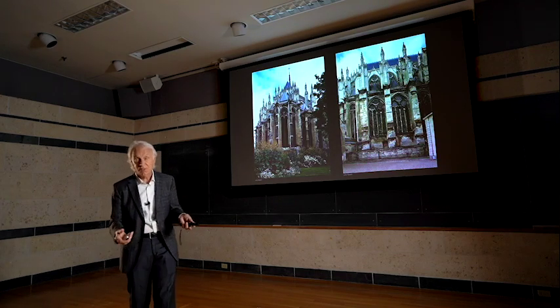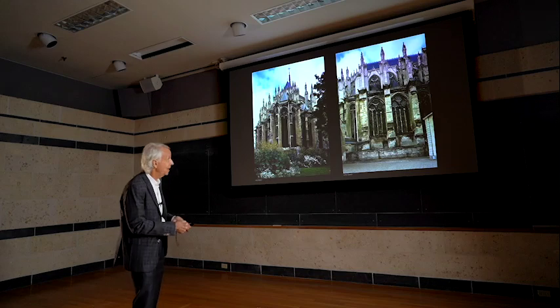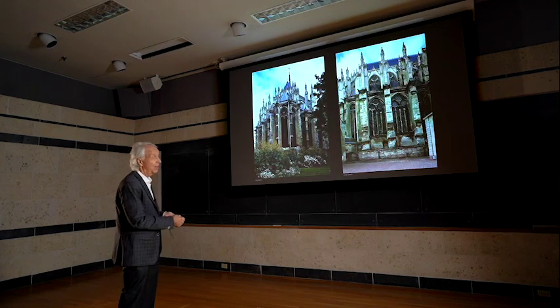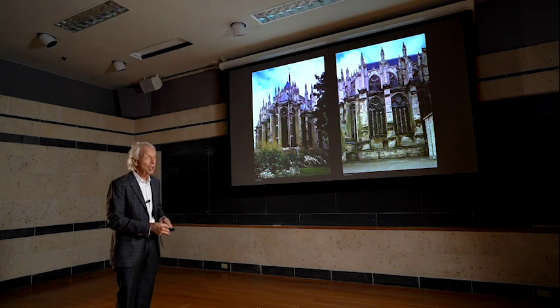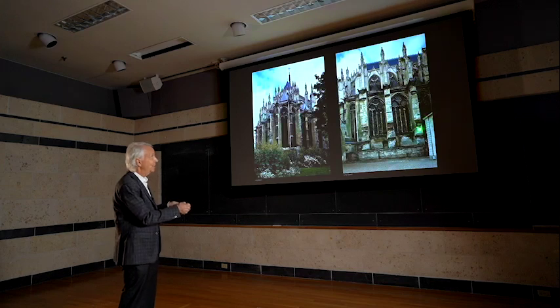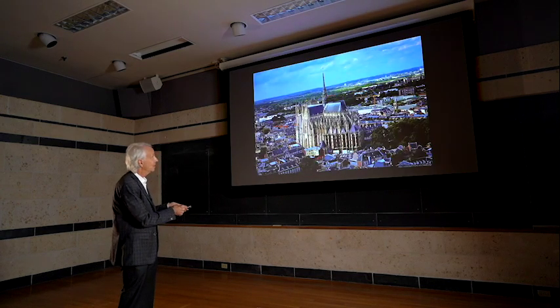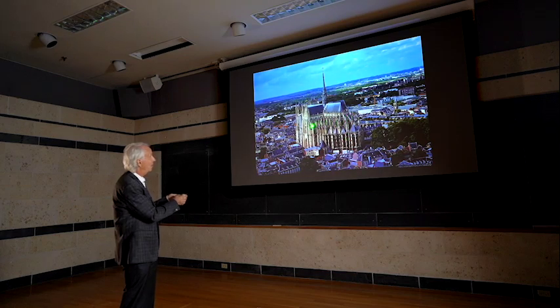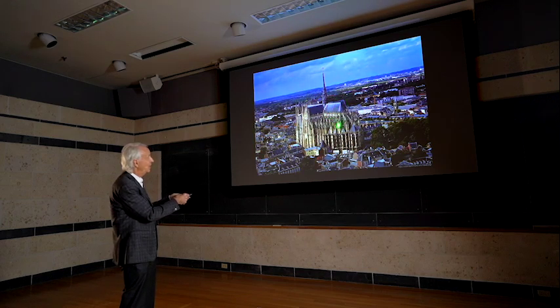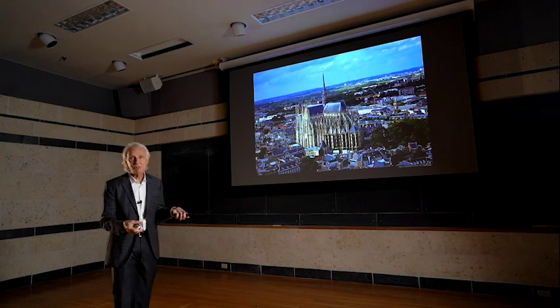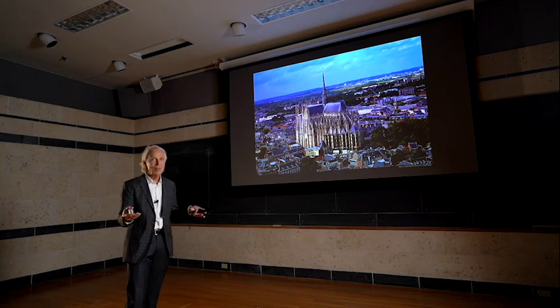For one thing, they've got these big aspirations. They want to have a masonry building, which means we have compressive loads and a bearing structure. And yet at the same time, they want to open up these big windows and have lots of natural light inside the building. So you can see in that photo how much glass there is in that wall. But that's got to be a bearing wall that's carrying those loads from the roof down to the ground, and opening up that much glass doesn't work with a bearing wall.